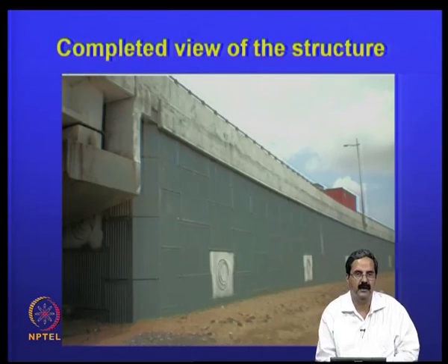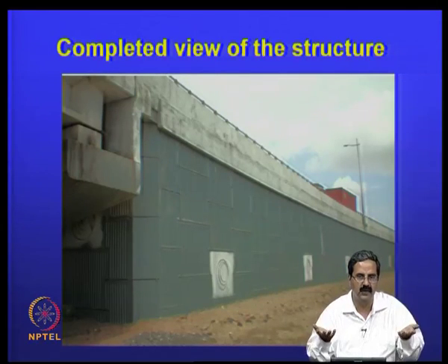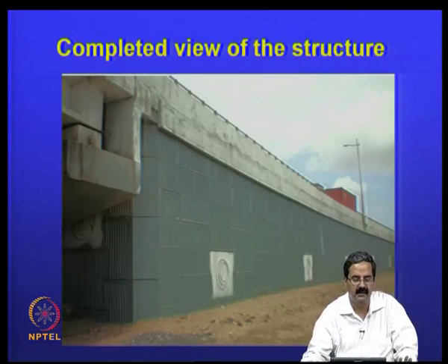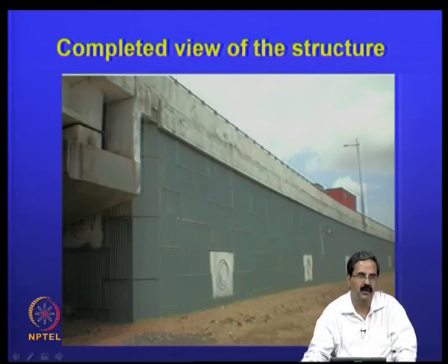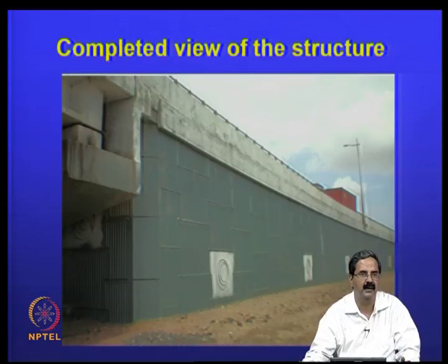say for example a void, you can put a geocell matrix at the top and make sure that all the load is taken care of only by the geocell matrix, the material, the foundation bed. We can call it a loading platform also. So you can see that it will be much more economical than trying to fill up a hole where we do not know where it starts and where it ends, right.